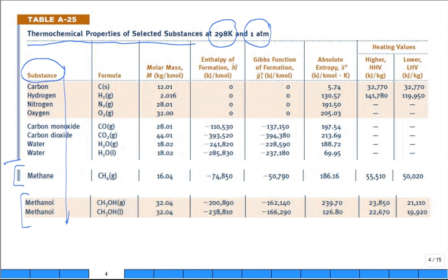So right away, you better watch out. Water could be in the liquid state at 25 degrees C, or it could be in the vapor state at 25 degrees C. True? It can. Water vapor can go out in a product stream, and as long as the temperature of the product stream is above the dew point temperature for that mixture, it's not going to condense. It'll go out as vapor. It doesn't say that the partial pressure of the vapor is 1 atm.